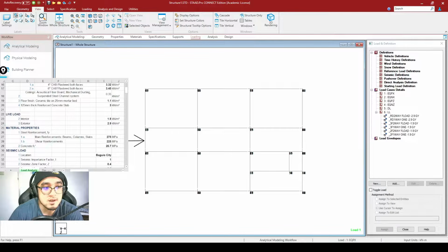And since this one right here is your column, these are to be your columns, and so on. All of these joints right here are columns. Your diaphragms would now transfer this particular load to each of these columns, so they are now to be resisted by these columns right here.